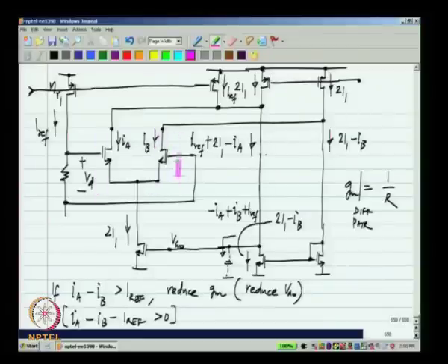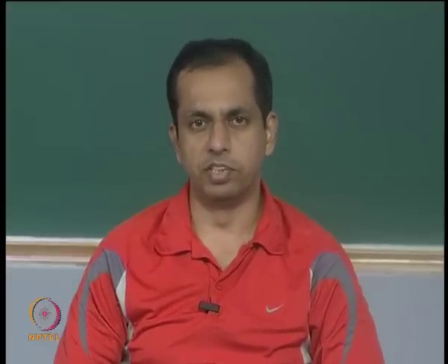whereas here I can make sure that the common mode input of this differential pair is the same as the common mode input of the differential pair I am using, okay. So this transistor and the actual transistor that I use will be suffering from the same body effect, or will be suffering from body effect to the same extent. So there will be no difference induced by body effect either. So this is a much more robust way of realizing a constant GM differential pair, that is a differential pair whose GM is constant over temperature, okay.